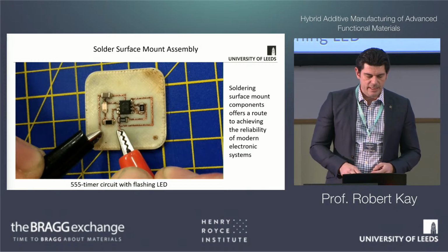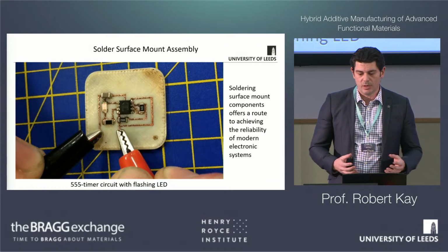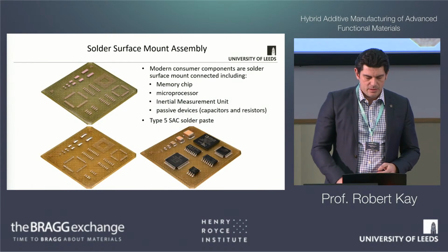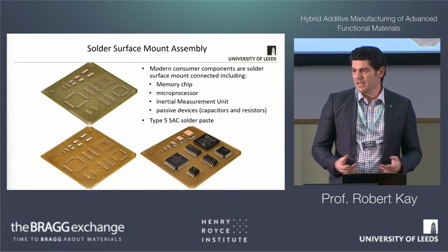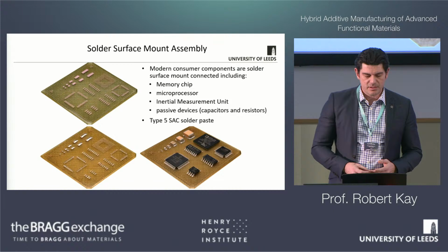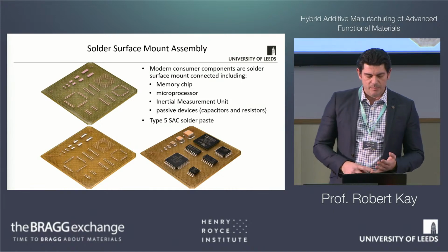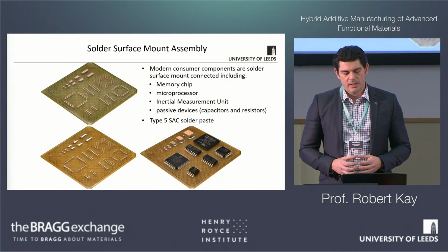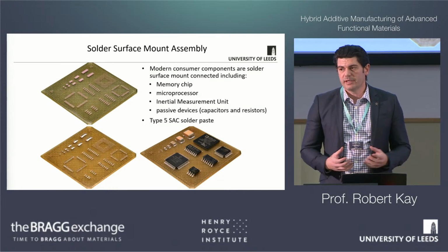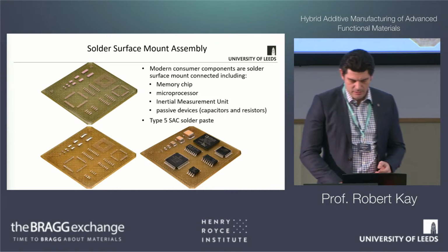So initially we just tested a simple 555 timer like I showed you before, and it worked, and we're very pleased. So more recently what we did was we actually looked at a range of different common commercial components, everything from memory chips, microprocessors, to sensors like IMUs and passive devices. And we've been using a Type 5 tin silver copper paste because that's the most common lead-free solder paste that's used by the consumer market.